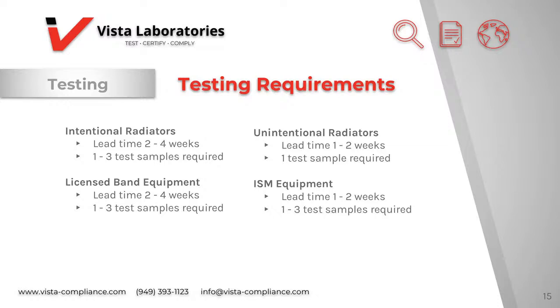Looking at the requirements for applicants in general, it's 1 or 2 samples, depending on how the measurements go. More samples may be required. Within each category, the lead time for evaluation and measurements varies. It also further depends on the complexity, supported different interfaces, functionality, and radio technology types. General equipment takes 1 to 2 weeks if it contains only one radio technology, such as Bluetooth or Wi-Fi. Composite devices containing more than one technology, such as a combination of Bluetooth and Wi-Fi, will take longer. Lead times will increase significantly if SAR or DFS measurements are required.